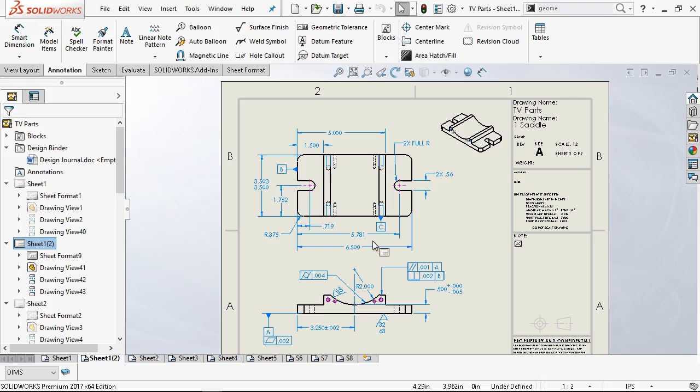All right. So on that delivery portion of it, on plus or minus 2 decimal places, like I mentioned, I'm probably going to go to the nominal dimension of a 2 decimal place because the stack-ups are kind of a pain to work with. We get, from a machinist standpoint, I think in terms of 3 decimal places.